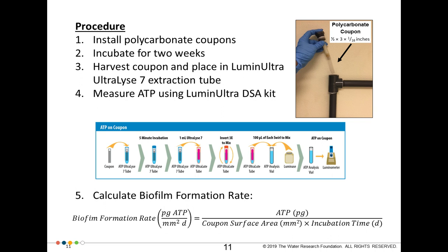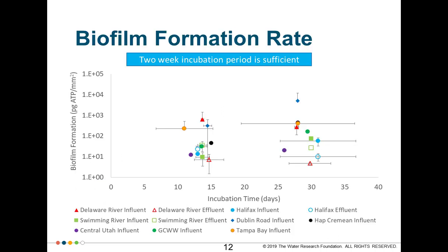So after we measure the ATP, then we calculate the biofilm formation rate by dividing the ATP concentration by the coupon surface area and the incubation time. So you might be asking, how long do we leave it in for? Well, we did an initial evaluation during the first half of our validation testing study to answer that question. Here we sampled over 4 months, collecting samples monthly from 8 utilities,